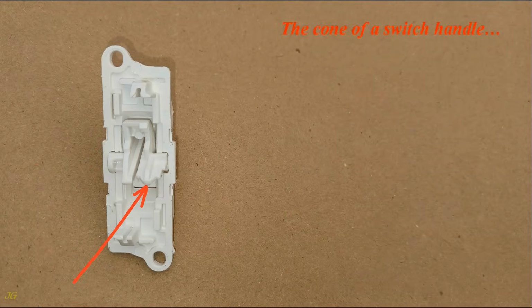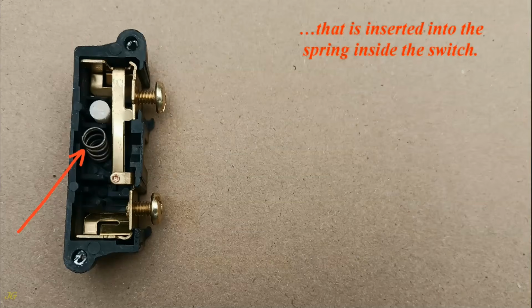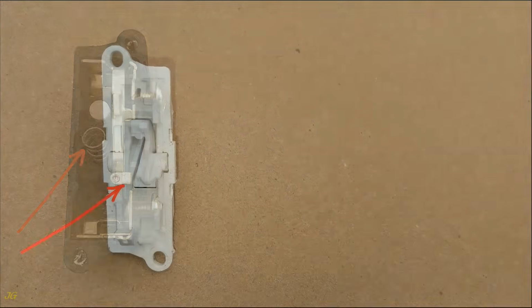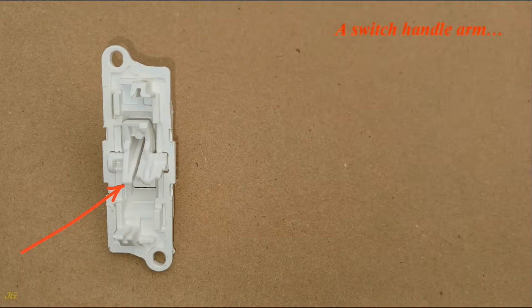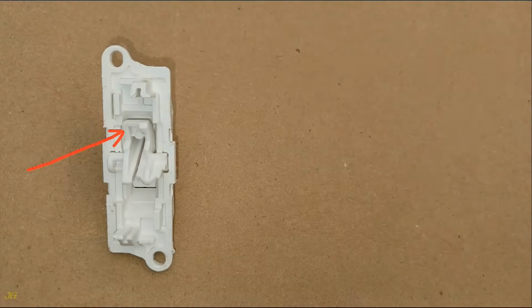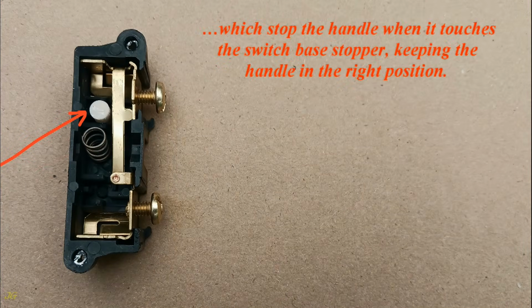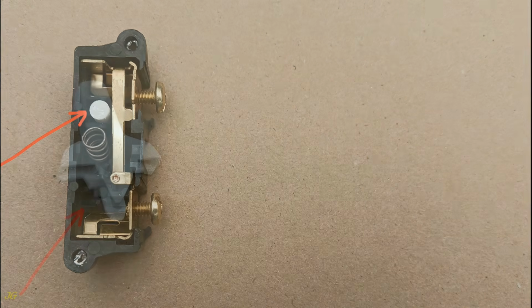The cone of a switch handle that is inserted into the spring inside the switch. A switch handle arm that depresses the switch spring contact when the switch handle is in one of the two positions. Stopper on the switch handle, which stops the handle when it touches the switch base stopper, keeping the handle in the right position.